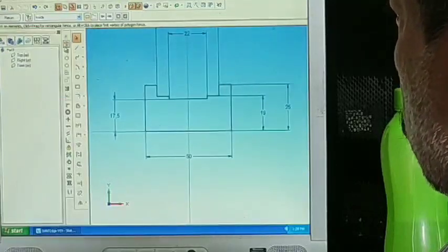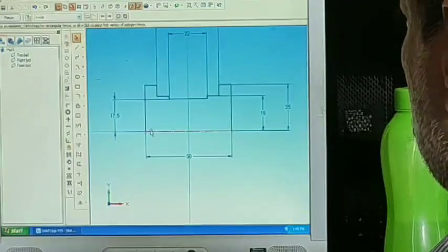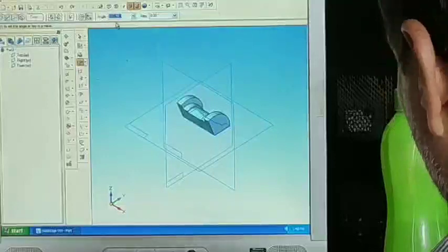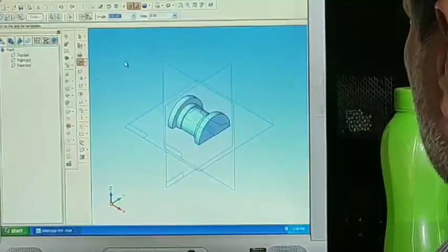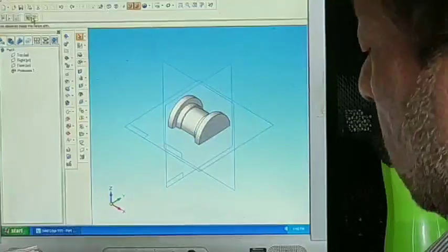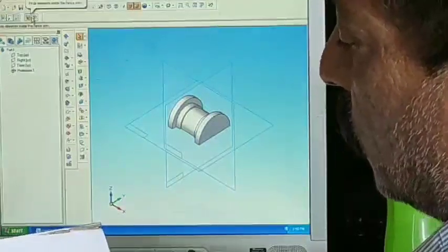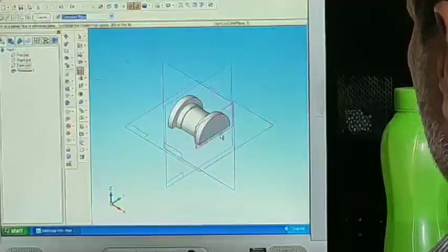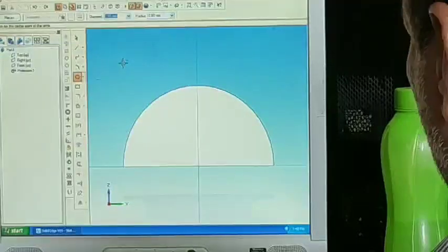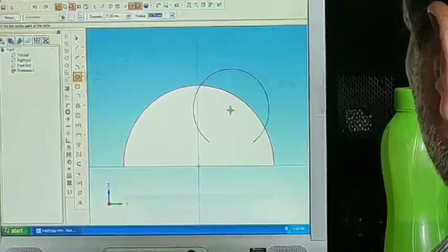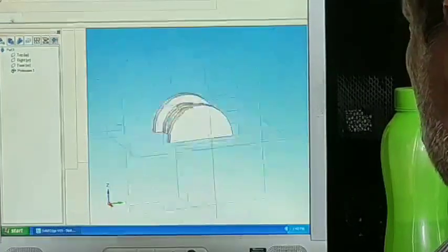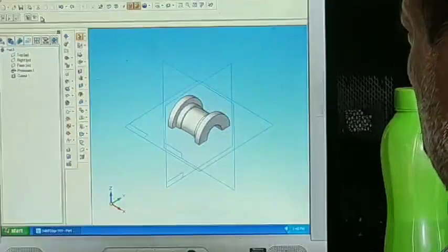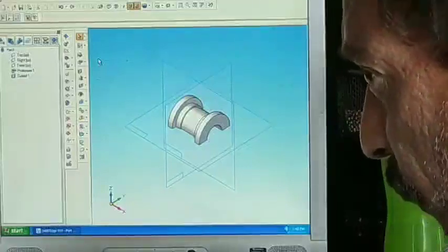Okay, revolved features must have an axis of revolution. So axis, return. So it is half, that is 180 degrees. Select as 180. Finish. So now there is a cutout of 25 diameter is there. So go to cutout option, select this face, circle, diameter is 25, fix it in the center, return, through all in that direction, finish, cancel. So now I constructed half of the bearing.